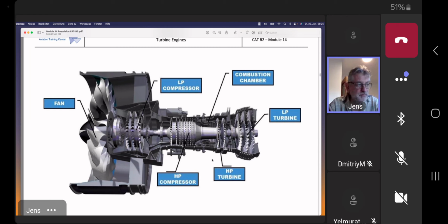So, but the point is, I can show it here. This is a point of interest. This is the last stage of the compressor. And here we would like to achieve a certain compression ratio. So big mass of air, very highly compressed. But if you want to consume more air here, the first stages have a bigger diameter, and you cannot turn them with the same RPM. Otherwise, you would exceed the speed of sound.